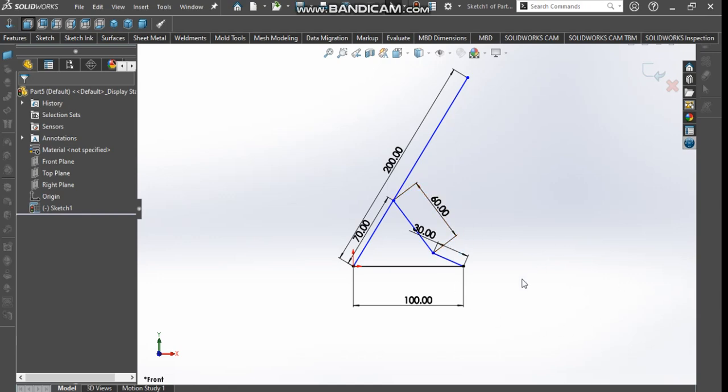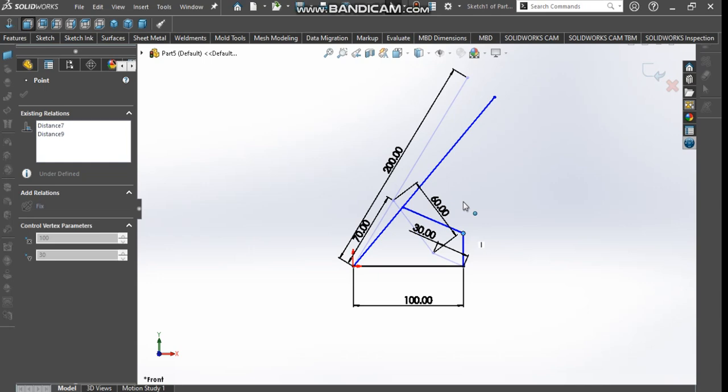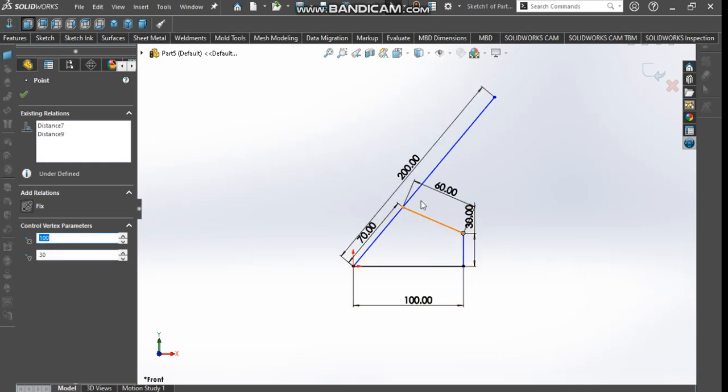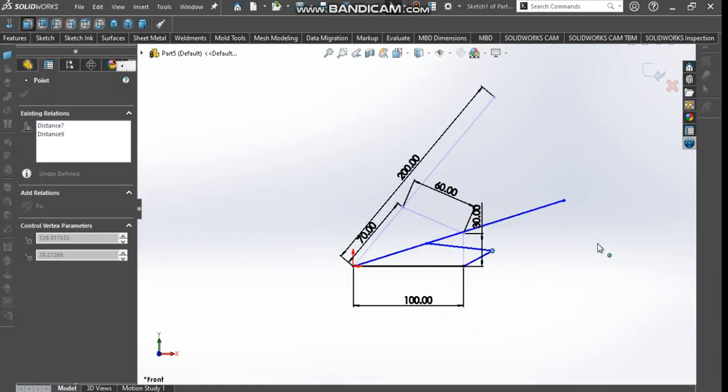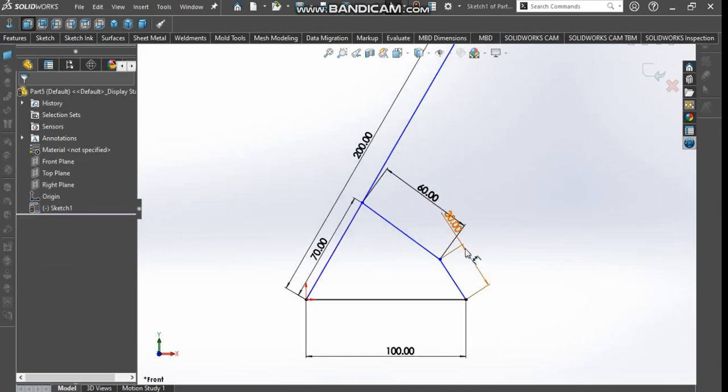An IC engine, you won't limit it to move only a certain angle; it will be moving a full rotation. So this is the crank. The motor is mounted here, then it's connected to this other link here. Let's say, for example, a windscreen wiper of a vehicle. You can see it will be moving back and forth as it cleans the screen. So you can see the advantage of a good four-bar mechanism, whereby the dimensions are appropriate. You can modify according to your need.